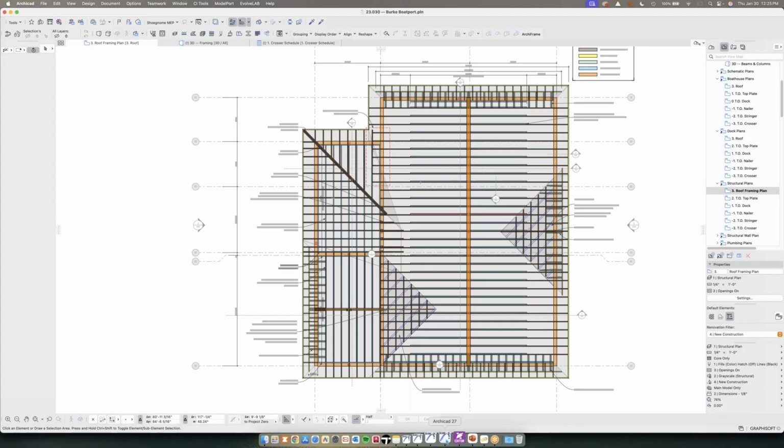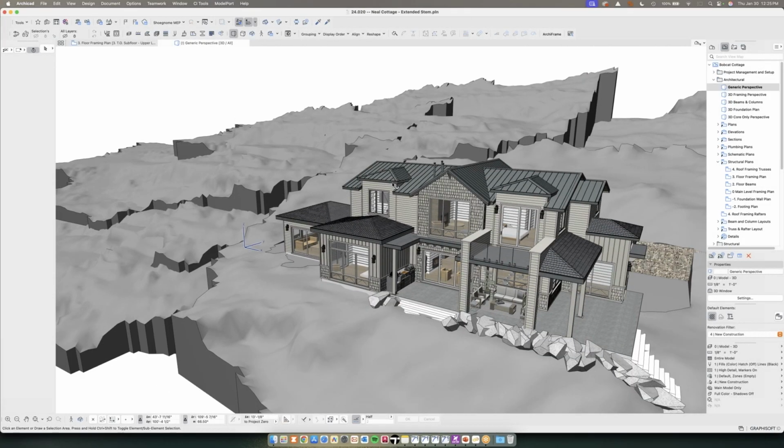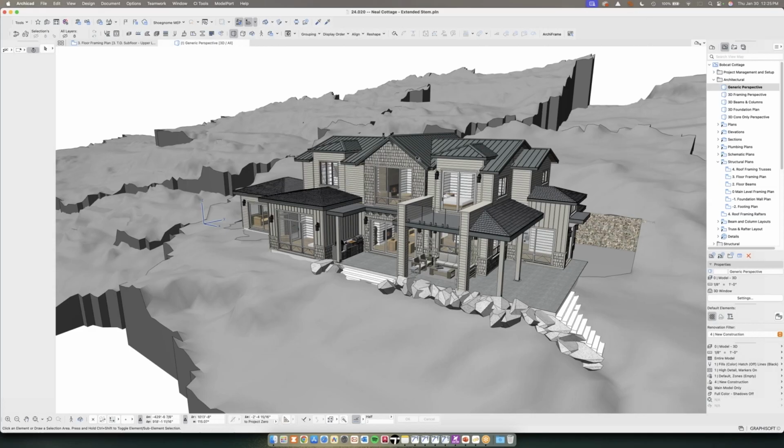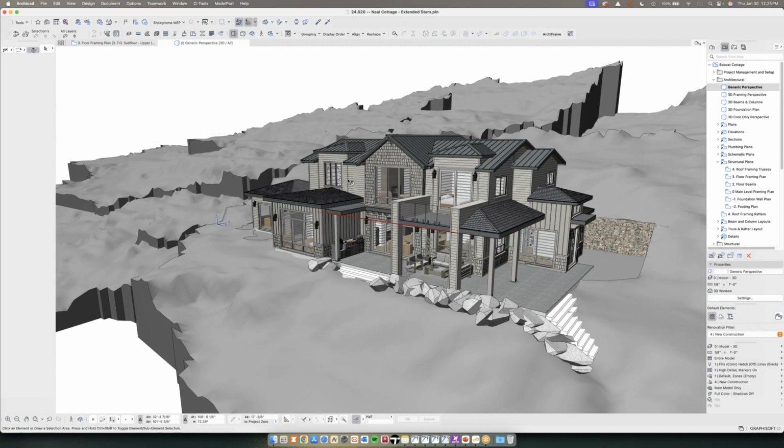The last one that I said I would show in more detail is this one here. So again, a relatively complicated build in terms of trying to integrate trusses and rafters and wall framing. There's a lot of elements in this building that require tall wall framing on the backside. So we're using something like a Weyerhaeuser LSL stud, if you guys are familiar with that.